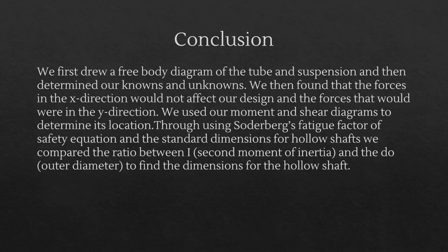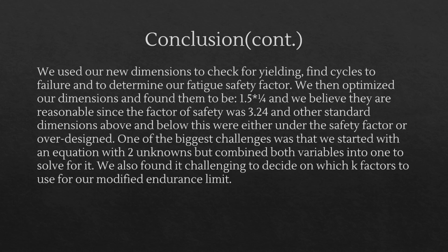Through using Soderberg's fatigue factor of safety equation and the standard dimensions for hollow shafts, we compared the ratio between the second moment of inertia and the outer diameter to find the dimensions for the hollow shaft. We used our new dimensions to check for yielding, find cycles to failure, and determine our fatigue safety factor.